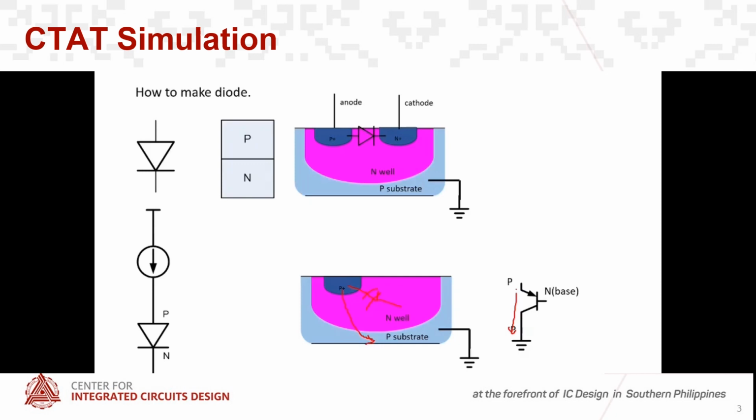It will affect other circuitry which is common to the substrate as well, because, as I mentioned earlier, the P substrate is the foundation for the CMOS, where all the circuitry is placed. So if we have other implants or circuits here, it would greatly affect the other circuitry. It would make the whole system malfunction, because it influences the substrate when we have large currents here. So that is a great problem also.